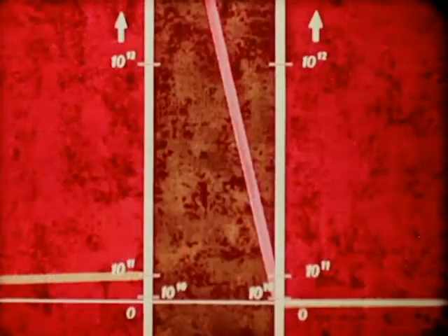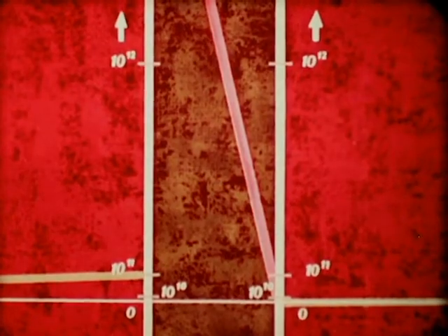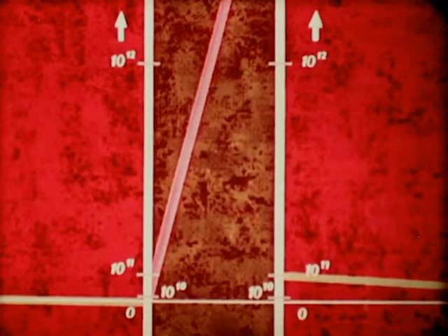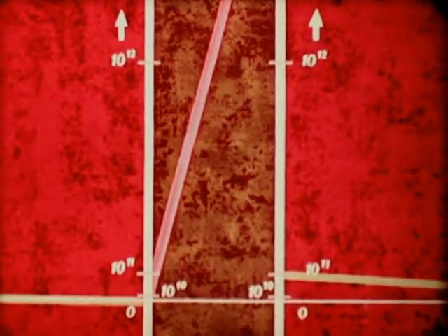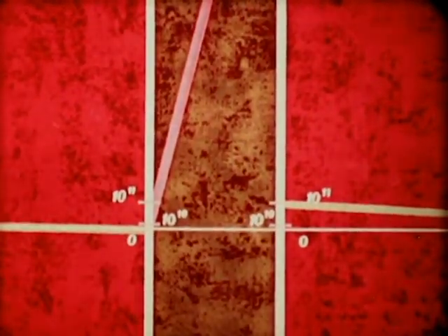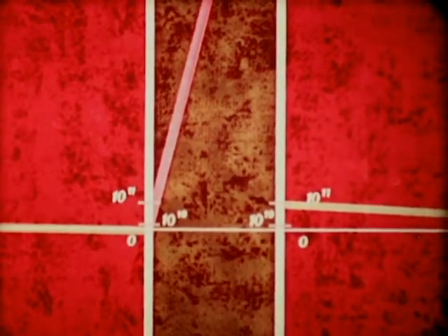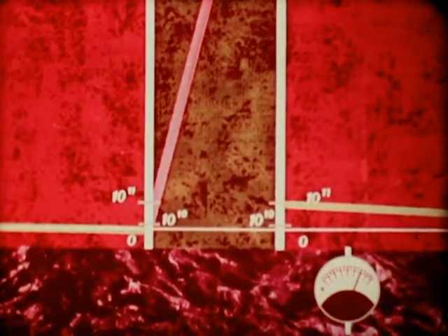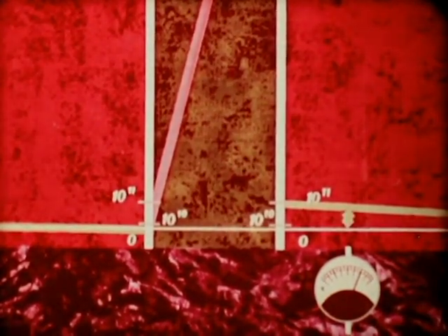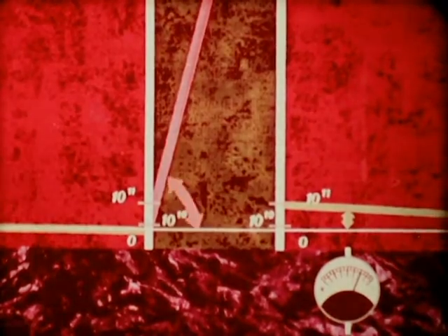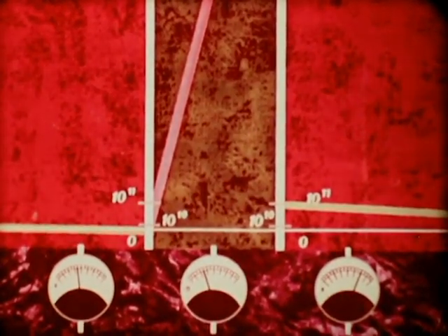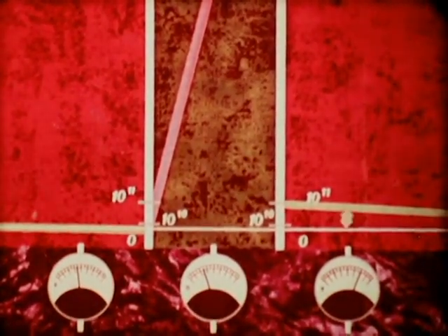This, of course, has the effect of reversing the minority concentration graphs. The three currents flowing are directly related to these concentration graphs: the collector current to the electron concentration in the collector and the hole concentration in the base, the emitter current to the hole concentration in the base, and finally the base current to the electron concentration in the collector.